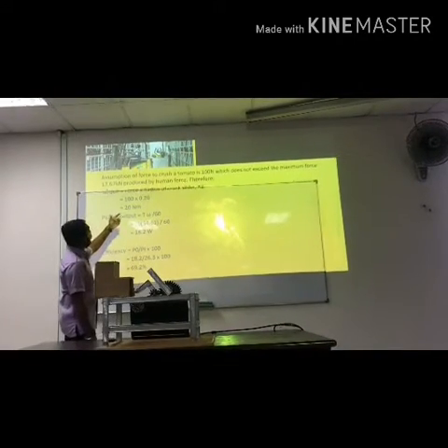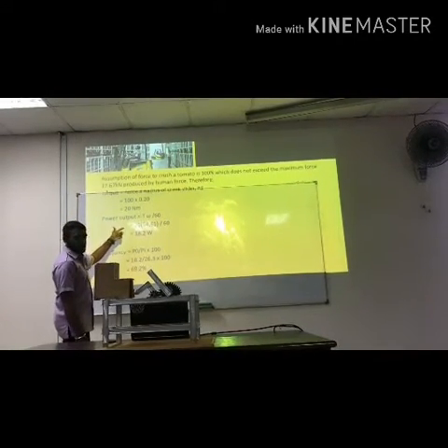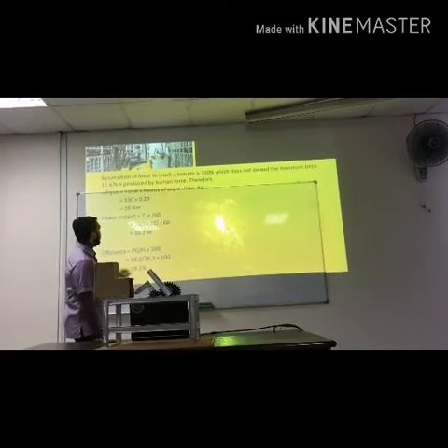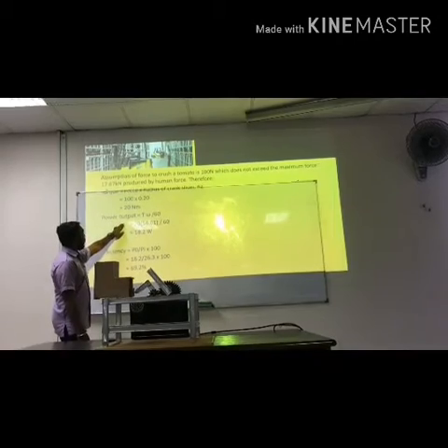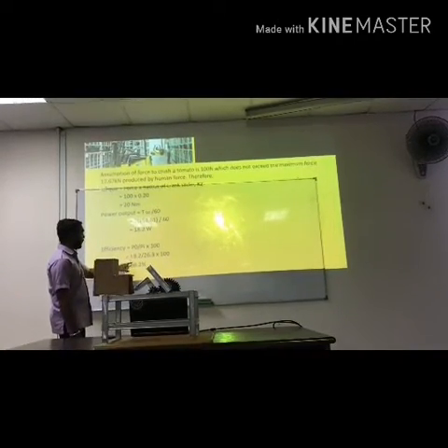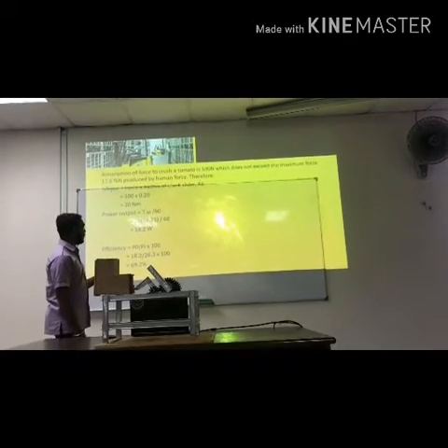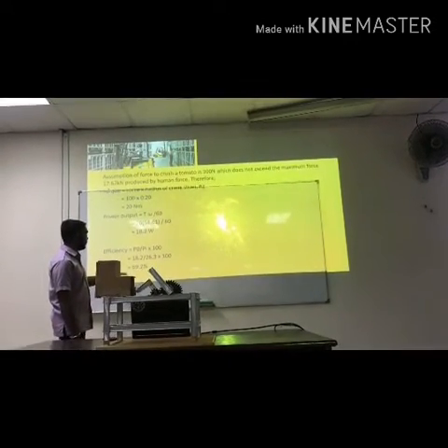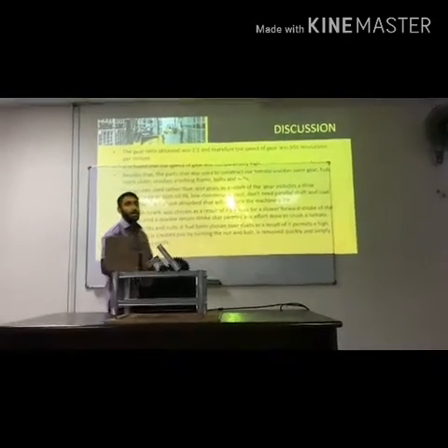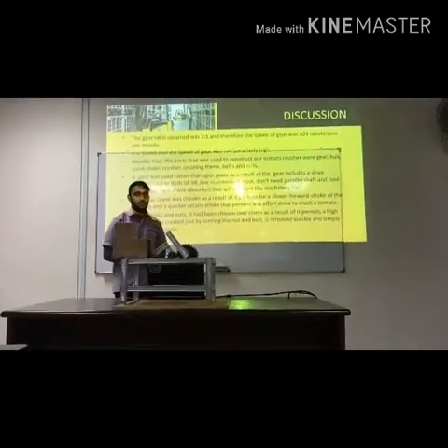Again we assume the force to crush a tomato. So we get the torque, which is force times radius, so it's around 20, and the power output is 18.2 watt. Efficiency, you can see, is 18.2 divided by 26.3 times 100, so it's 69.2%. Okay, that's all from me. Now I'll pass to my groupmate for the next part.